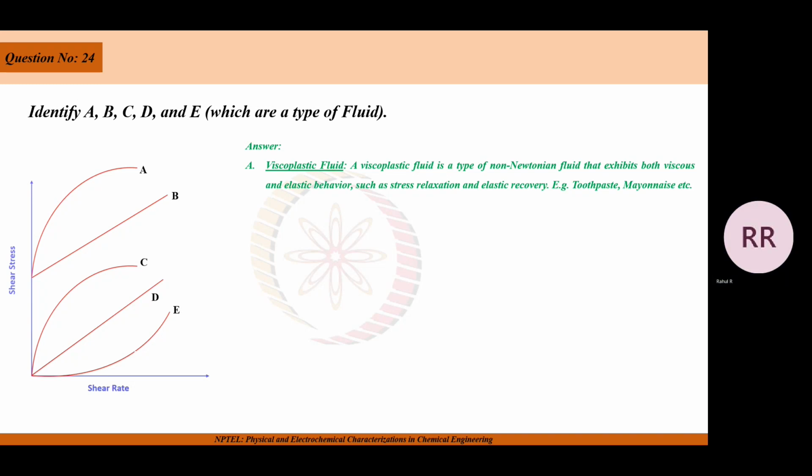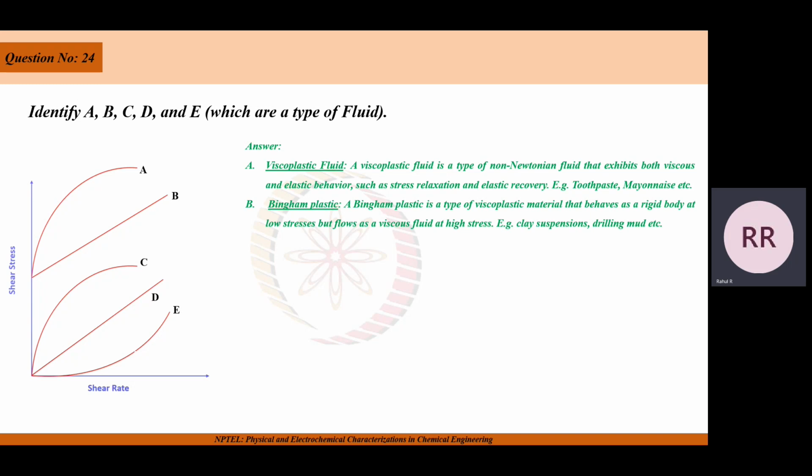Here we can see that even though the shear rate is zero, the shear stress is not zero. And this exhibits both viscous and elastic behavior, such as stress relaxation and elastic recovery. The examples are toothpaste, mayonnaise, etc. B corresponds to Bingham plastic.